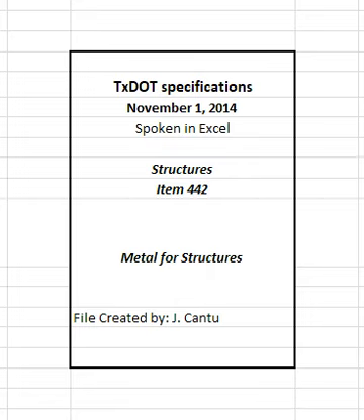2.5 Steel tubing. Provide steel tubing that meets ASTM A500, grade B unless otherwise shown on the plans. Tubing that meets API standard 5L, grade X52 may be used if produced by a mill listed in the standard API specifications as authorized to produce pipe with the API monogram. Hydrostatic tests are not required for API 5L steel, and instead of an MTR, the manufacturer may furnish a certificate for each lot or shipment certifying the tubing meets the requirements of this section.